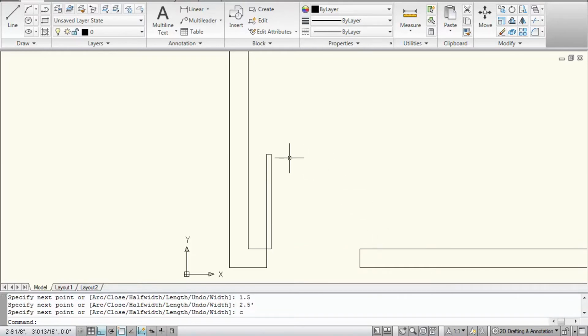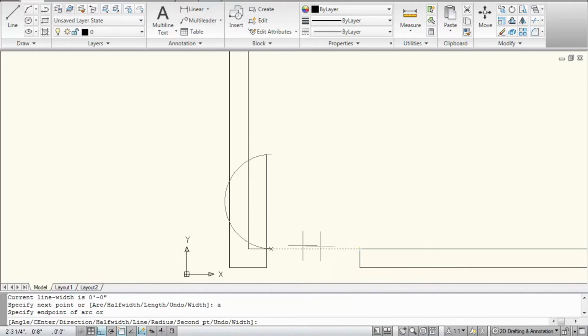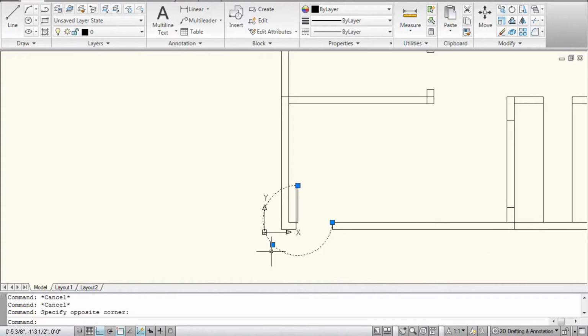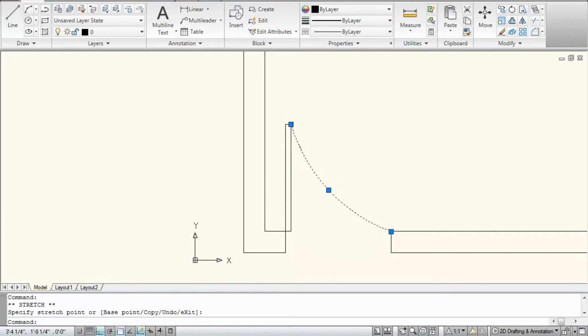So there are two ways to do that. Some people will just make a polyline like this, click there, and then show an arc by pressing A, going across like this, and then putting it like that. Just keep making it work.